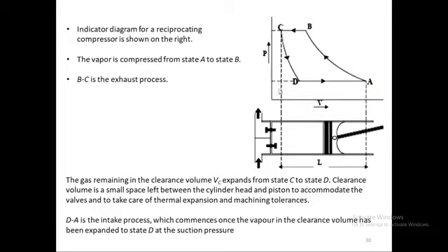But the dash line is showing the clearance volume. So the piston can reach up to this dash line. It cannot go beyond that, because if it does, it will hit the valves and damage your compressor. We don't want the piston to hit the head or the valves in front of it, so this much volume has to be left. This is called clearance volume, and from top dead center to bottom dead center, or vice versa, the volume sucked by the cylinder is called the swept volume.